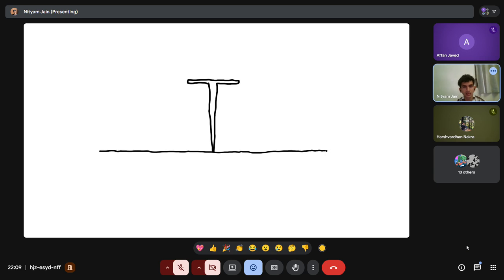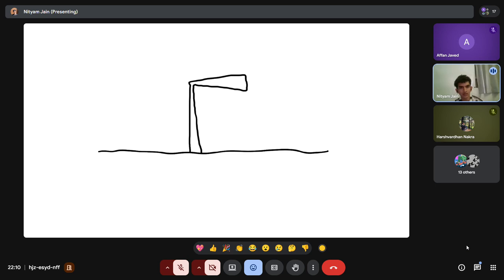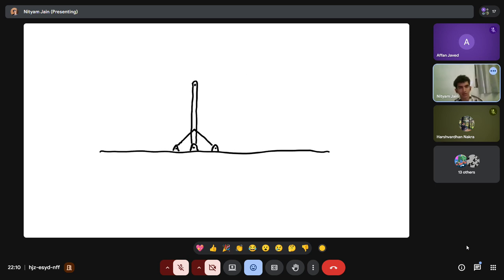Let's say this is a canopy sort of thing. Because the member is so thin at the bottom, this can happen. So basically here we can say the bottom is acting like a pin joint, not like a fixed joint. Even if it's welded to the ground or bolted to the ground, it doesn't matter. The thin member profile allows that pin behavior, which will lead the canopy to do this, or like a cantilever, if we see, it might do this.